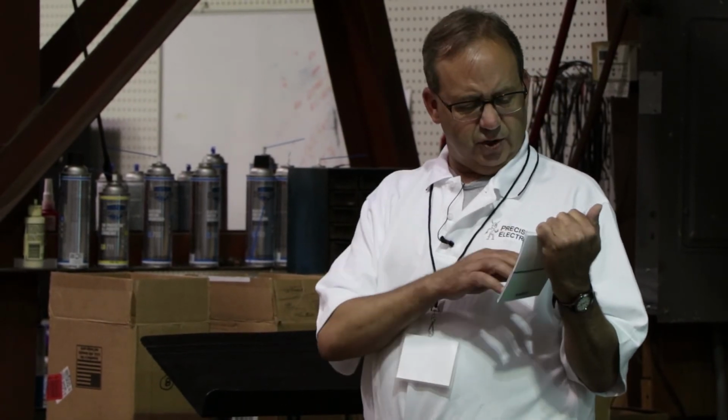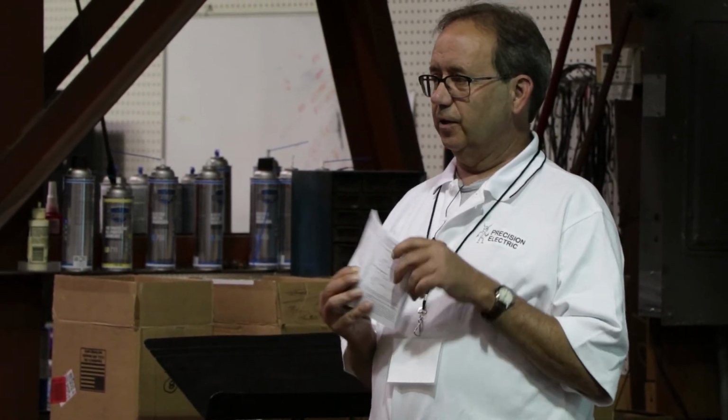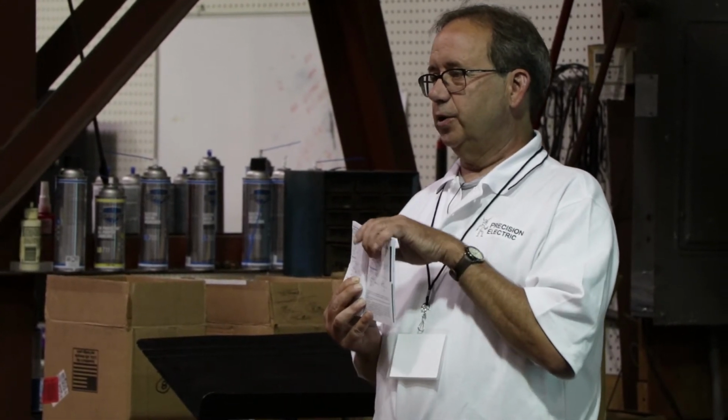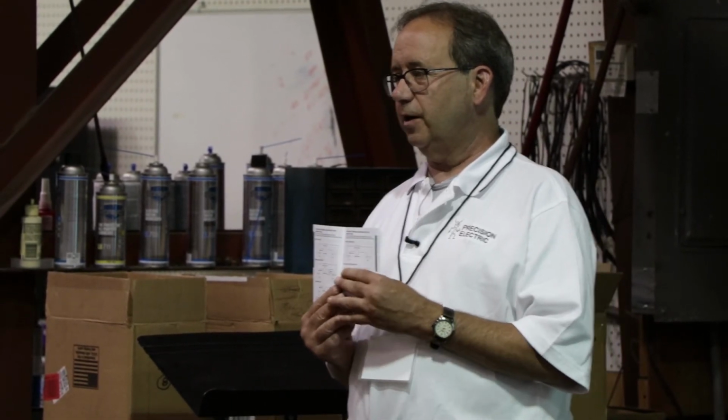And then you got to change the A1 and A2 around. So it could be real tempting just to change the whole circuit by going to your drive and pulling out A1 and A2 and switching those. But if you do that, you're changing the polarity of that series field in relationship to the shunt field, which is going to differentially compound the motor's stationary field. And when you pass current through it, the higher the current, the more it's going to cancel it out. It's connected in series with the armature.